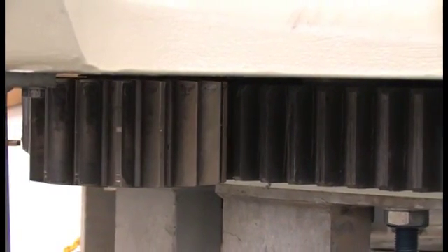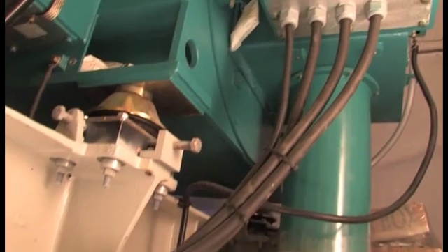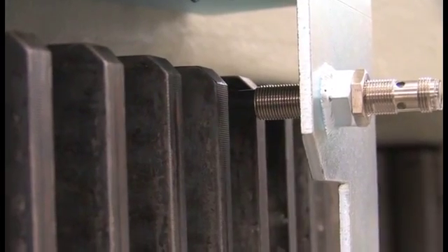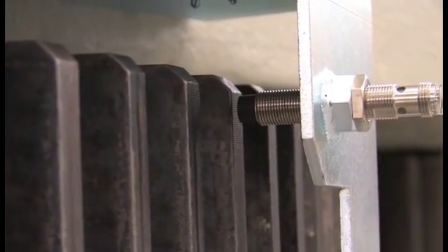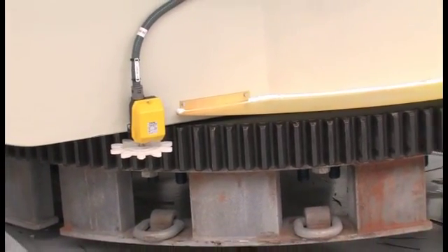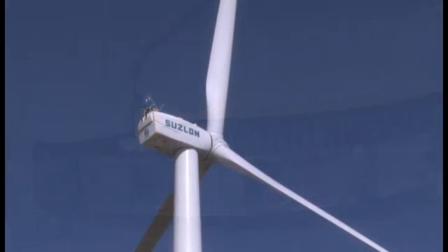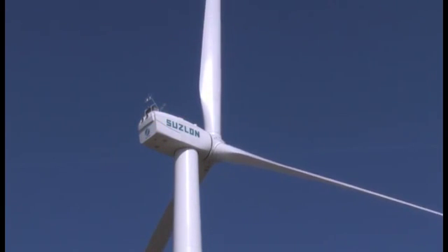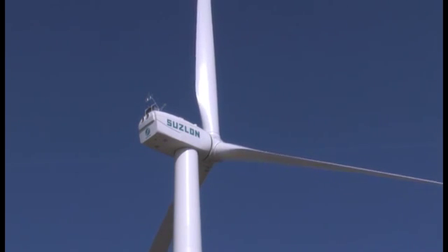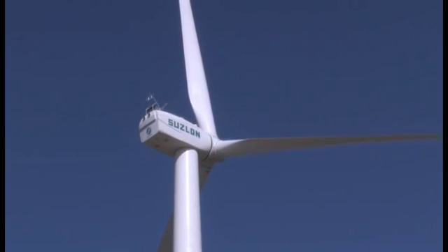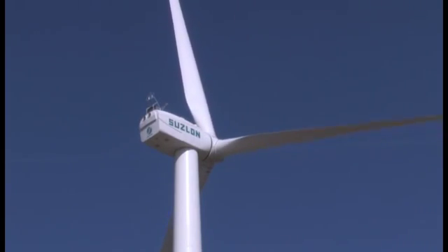As the nacelle tracks the wind, the flexible power cables become twisted, but might untwist as the wind changes direction. Sensors detect nacelle rotation, and the controller counts the revolutions. If the twist becomes excessive, the controller will put the turbine into a stop state and rotate the nacelle to untwist the cables. If the nacelle is pointing 180 degrees away from the wind, the controller will determine which direction will untwist the cables and then turn the nacelle in that direction to realign it with the wind.